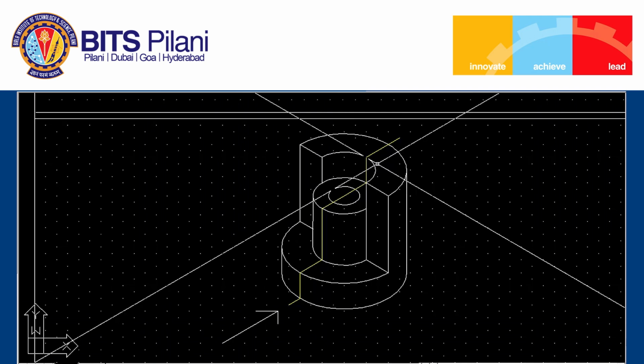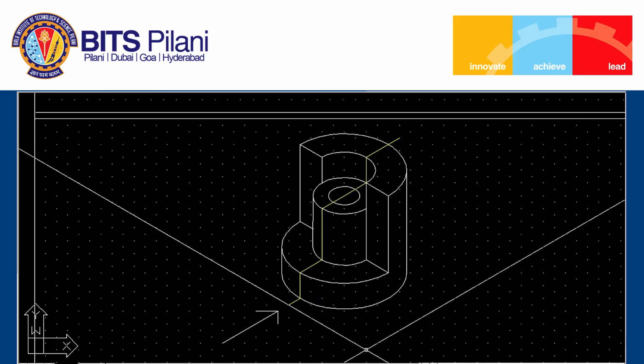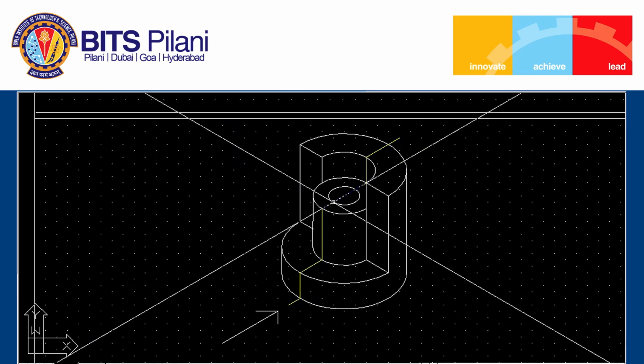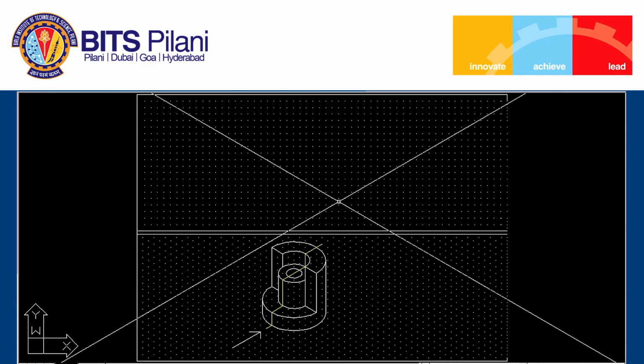So, while drawing, we will start with the view where we can see the circles. It is easy for us to draw the view. So, in the top view I can see the circles. So, the outer curved surface, then this cylindrical portion that we can see in the top view. So, let us start with the top view.